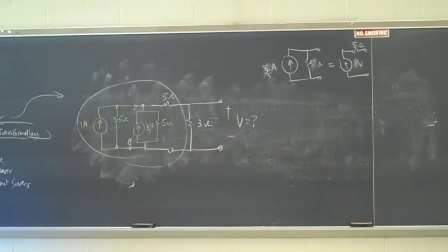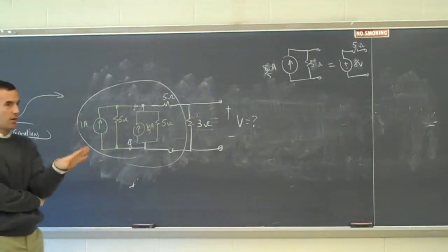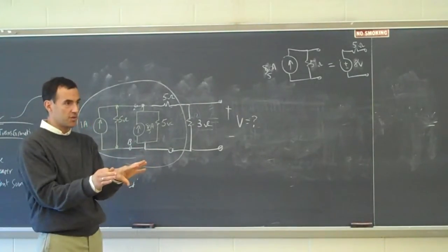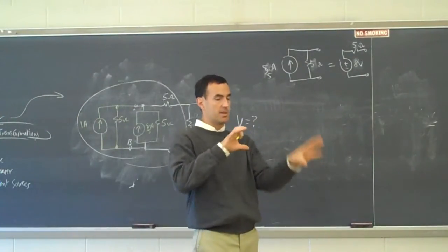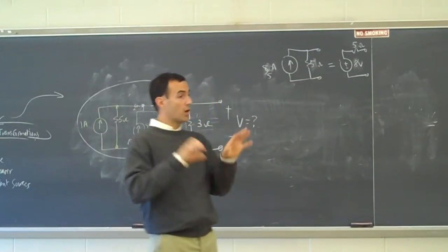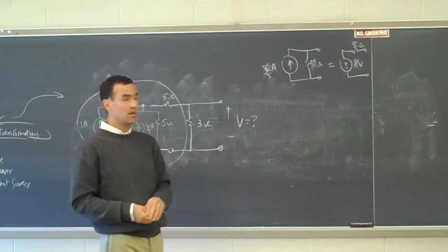Edgardo: So when you change it from Thevenin to Norton, for Norton, they always have to be parallel from the current source? Yes, yes. For the Norton, there will always be a current source in parallel with a resistor, and for the Thevenin, it'll always be a voltage source in series. We're claiming those two configurations are equivalent if we pick the right sizes.